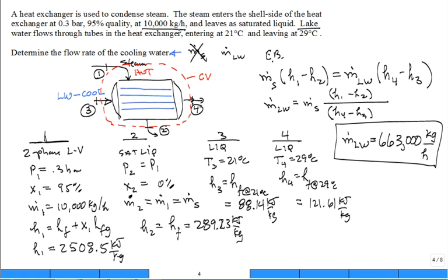All right. How do we cool power plants in the state of Texas? We build a lake and we dump the heat to the lake. That's pretty common. If you have a river nearby, you can take some from the river and then dump it back into the river downstream if the river flow rate's constant, etc. Our river flow rates, probably not as well. We actually sometimes will pump it out of a river into a lake and then let the lake level be constant. Okay. Any questions on that problem?